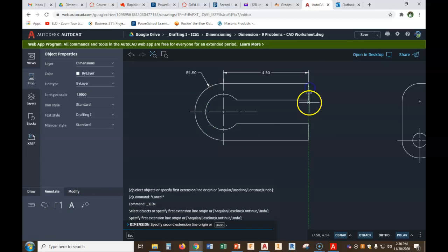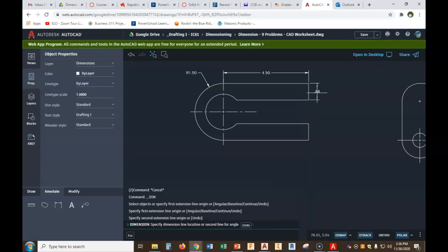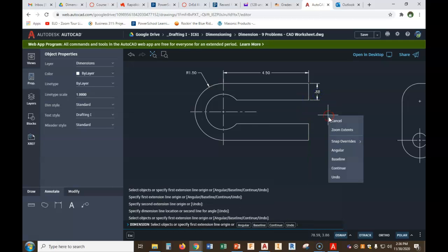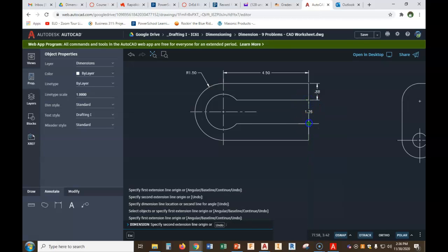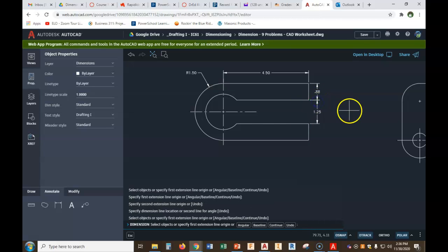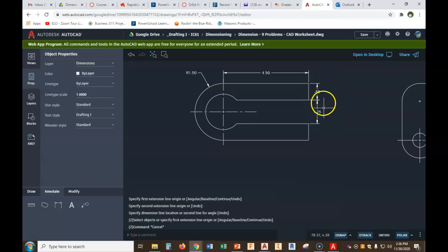Well, let's locate from here to here and drag out. There it is. Now, because it's a cut, I don't want cancel. I want to stay in the command. Click, click, and drag out and line up your arrows. Click. Come in 7/8 and make a 1 1/4 inch cut. Well, how far? When you hit the hole, you're done. We don't have to give a dimension there. Okay? The only thing we've got left is that actual diameter.